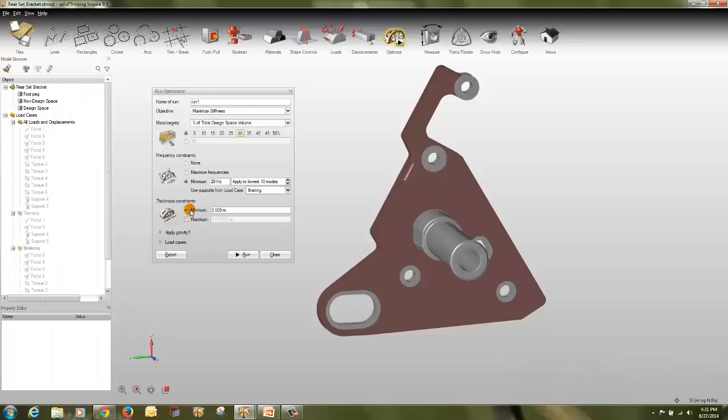Whatever you specify here, if the minimum thickness is not active, you cannot have the maximum thickness directly. So the minimum thickness is 3 times the average element size, and the maximum thickness should be 2 times the value entered in the minimum thickness. If I turn on maximum and enter 0.0001, it will give a warning. You can see the maximum thickness should be set to at least 2 times the minimum thickness. So change it to 2 times, and it will automatically change.